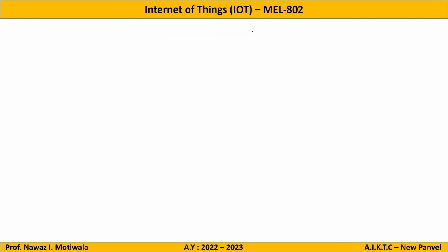Okay, starting with this. In any program, our first step is to initialize the pins. So if I draw a 7-segment display, let us say this is A, B, C, D, E, F, and G. And there is one more small LED here, known as data pointer or display pointer or decimal pointer, and let us say I am naming it as H. Because there are 1, 2, 3, 4, 5, 6, 7, and 8 LEDs, we need to use 8 pins on the Arduino board.